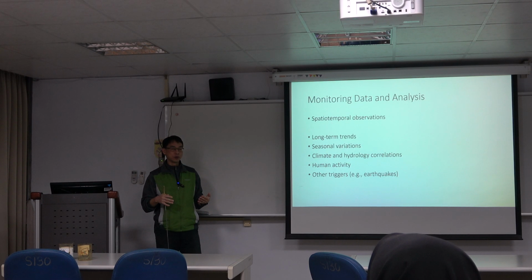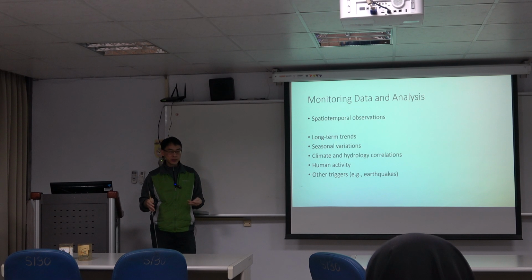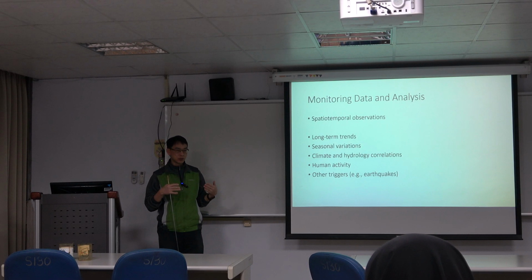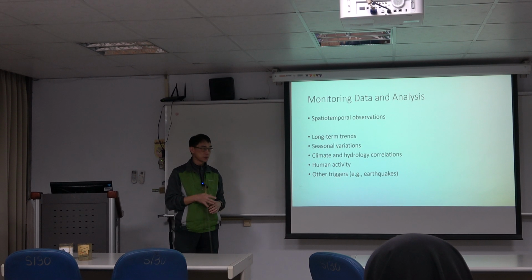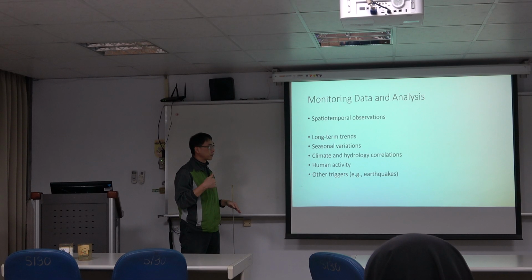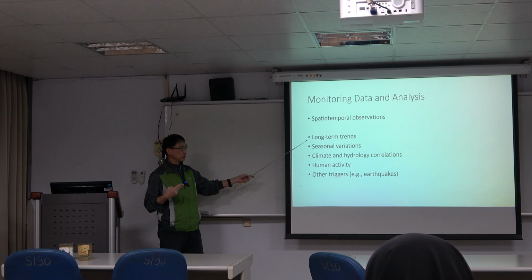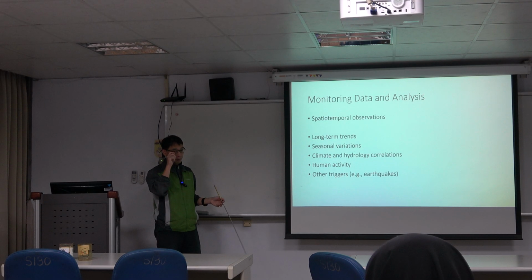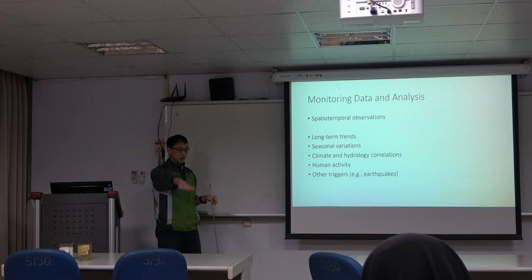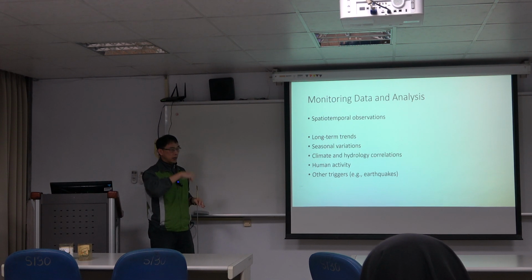So you need to control your pumping. Or in a hot spring area, if your groundwater level continues to decline, you need to be careful about that issue. So time series analysis is very important. Okay, so we commonly see these two, long-term trend and seasonal variations. The long-term trend lets you understand the background, whether it is uplifting or declining. And the seasonal variation will let you see how large the variation might be. As I mentioned, they could be connected to water resources or engineering work or hazard issues.